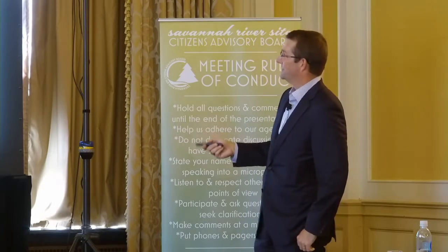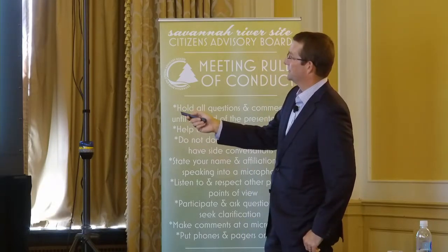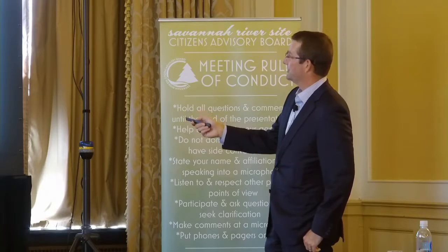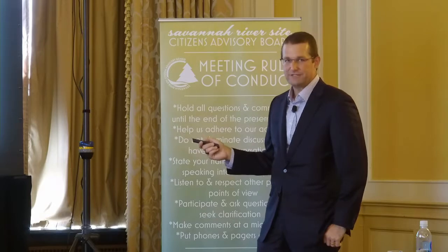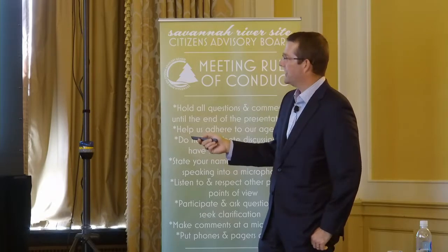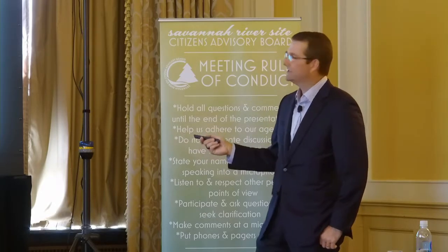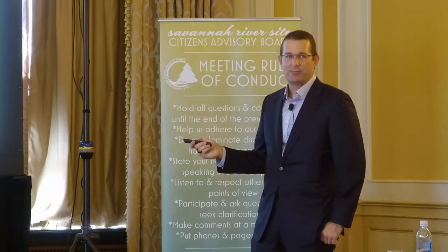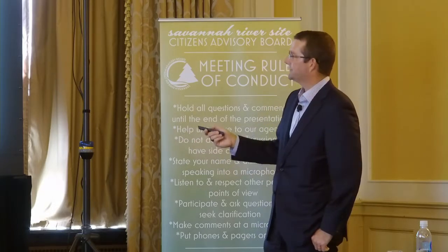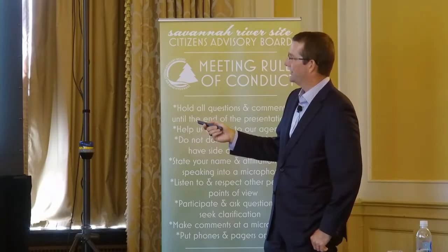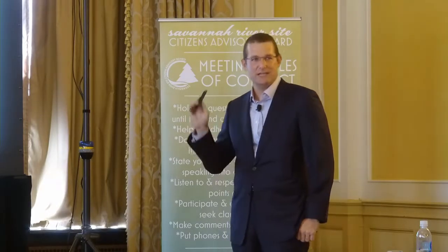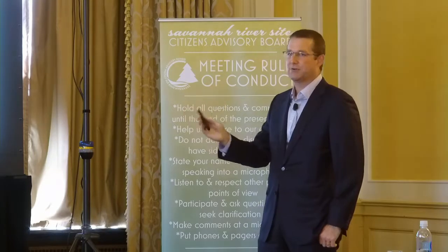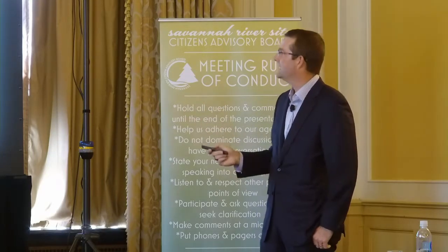This is our hopper. So, okay, I lied. We're taking this picture from the bottom now. So the mixer platform is right up here, but it discharges to the hopper. Again, this is about a 450-gallon vessel. It has a conical shaped bottom. It is agitated, and we normally operate it at an operating level of about 300 gallons. It is supplied with a number of spray jets and flush nozzles inside to keep the interface clean. Any place grout might have a tendency to accumulate.